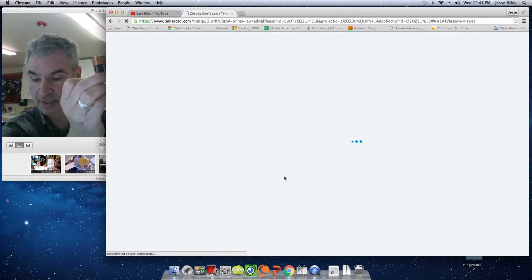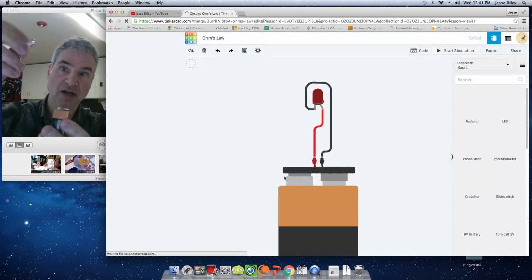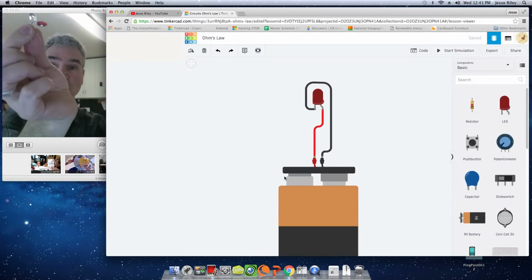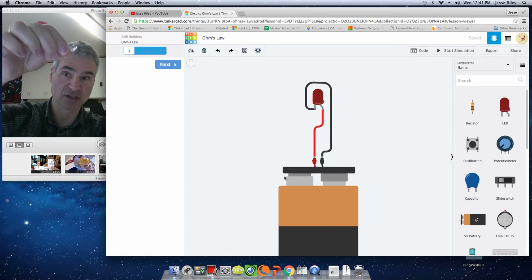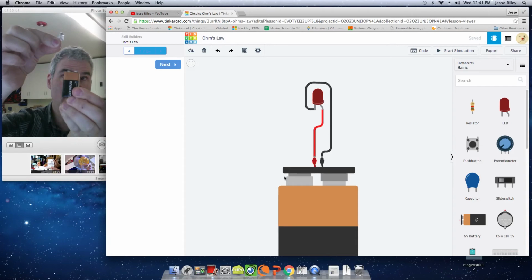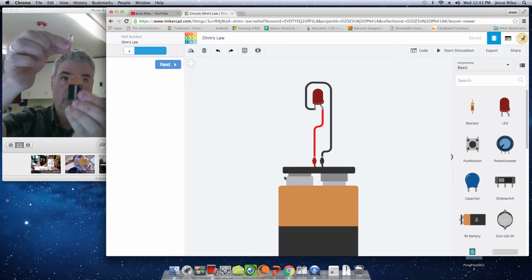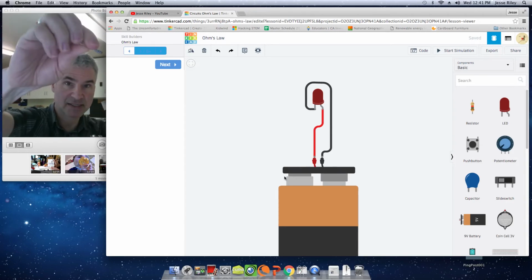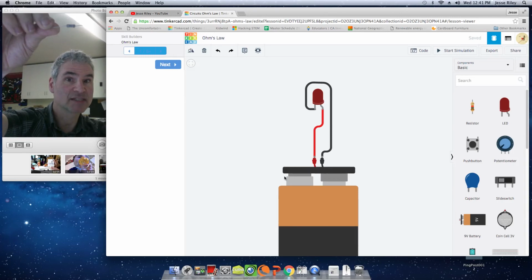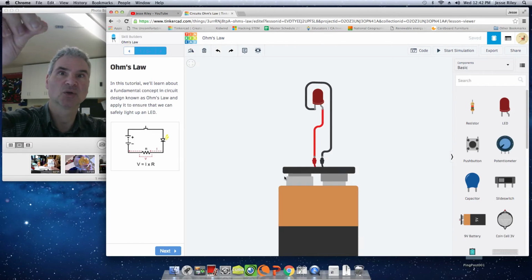is great. So if we did the same with LED, which you've seen before, there's the LED, you know that we use 3 volts for this sort of LED. If we added a 9-volt battery to it, it would blow up. And so what I'm going to show you how to do is to use a resistor and changing the resistor values here to help protect components in your circuits.